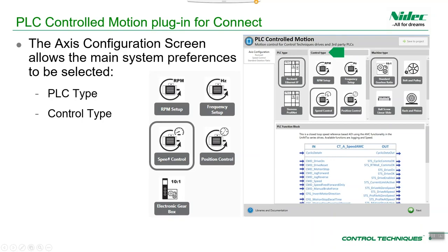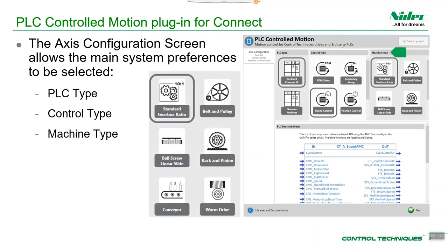One is a simplified speed control interface, but in real engineering units, whatever user unit that you'd like to choose. That could be, say, millimeters per millisecond. Then a position control interface that gives you indexing type capability, and lastly an electronic gearbox interface, which gives you the ability to follow a real-time motion reference over synchronous communications.